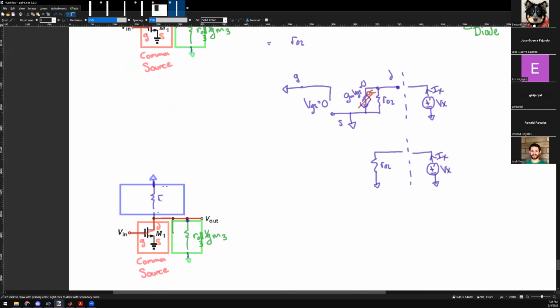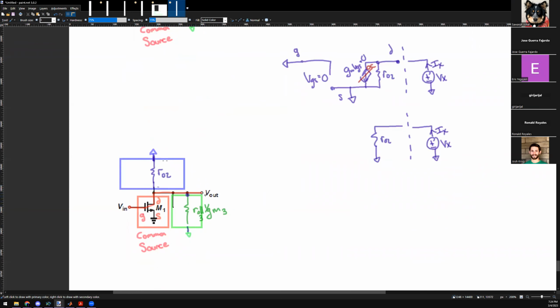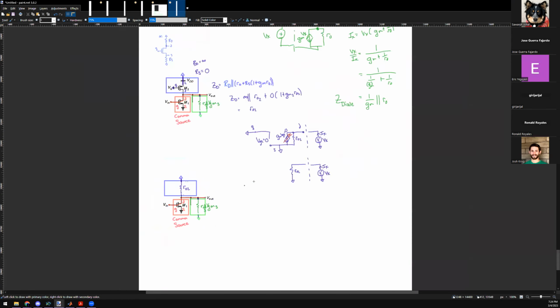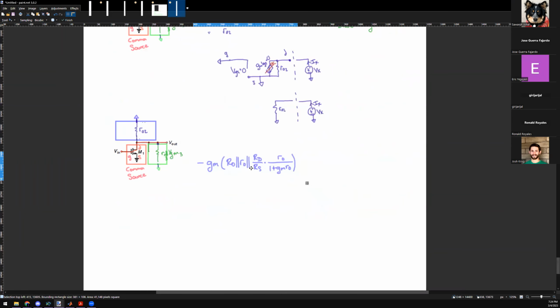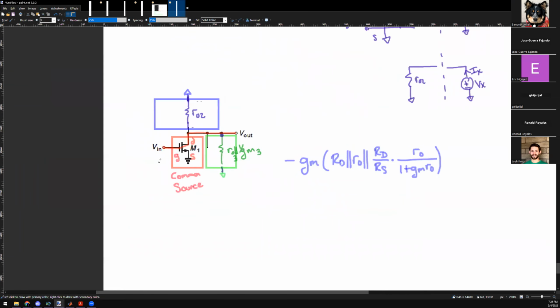Any questions here? So now we simplify those two blocks, and I just need to figure out what the common source gain is. This is just one common source stage. So I go to my cheat sheet, I go to common source, I take this guy, and I copy it down. Okay, which MOSFET am I going through right now? I'm going through M1, right? So the voltage gain for this stage is gm1 and R naught 1. Just make sure you subscript to respect the 1, okay?